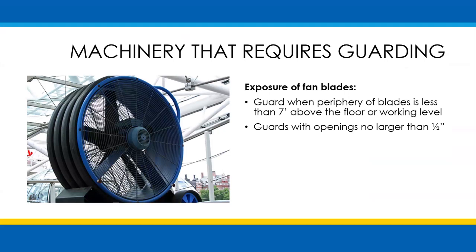Fans that are less than 7 feet above the floor or working level must be guarded. Fan blade guards cannot have openings that are larger than half an inch.